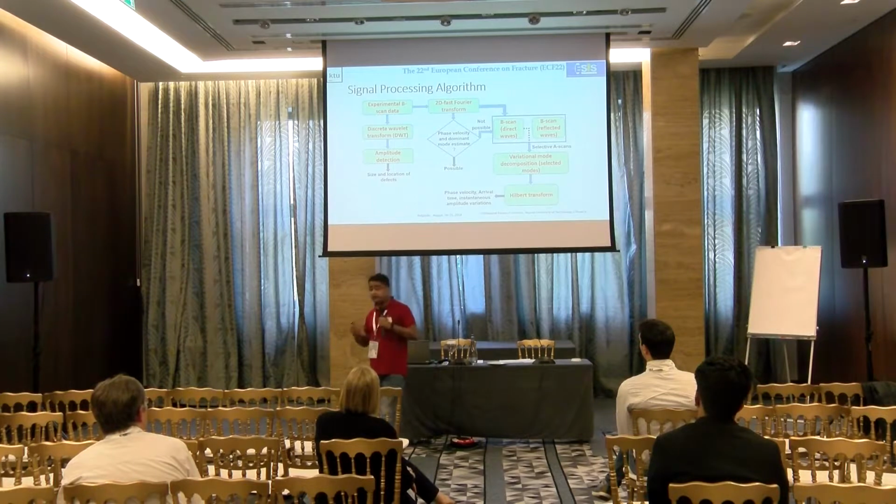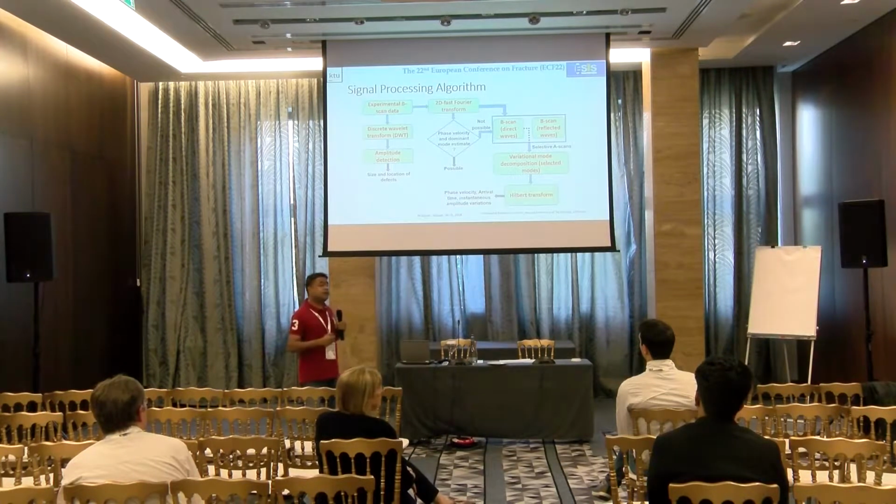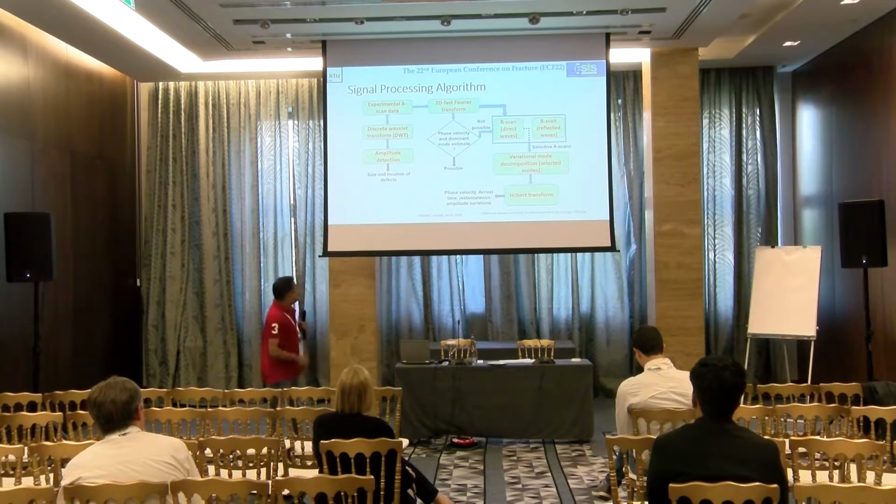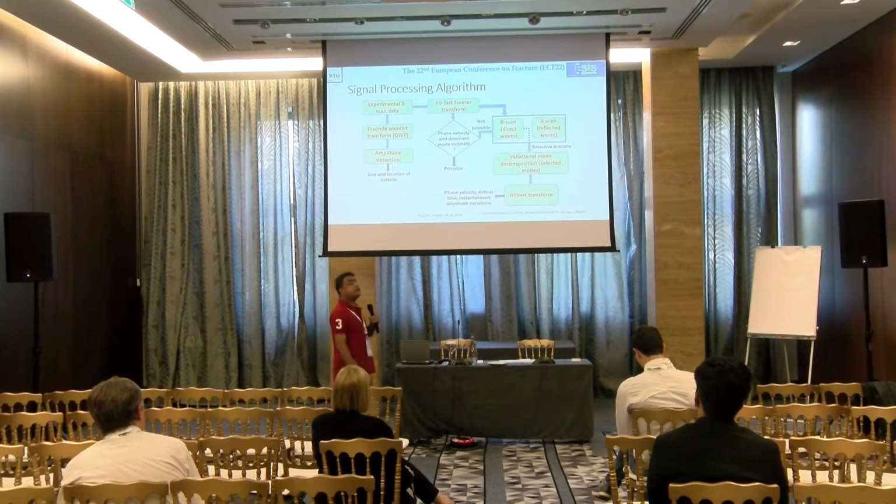An intrinsic mode function is defined such that the difference between the number of extrema of the signal and the number of zero crossings of the signal is at most 1, meaning either 0 or 1. So we will discuss that. And then the Hilbert Transform will be applied to extract the instantaneous characteristics of the signal. We cannot apply the Hilbert Transform without using the variational mode decomposition, because we need a monocomponent signal, otherwise the Hilbert Transform will not work.